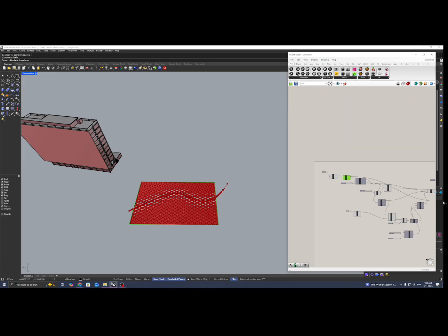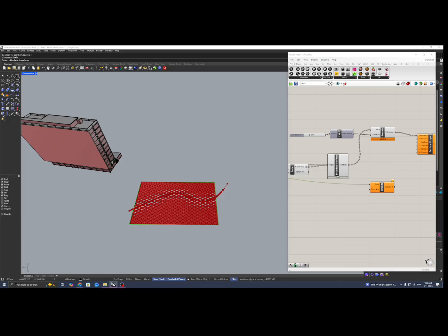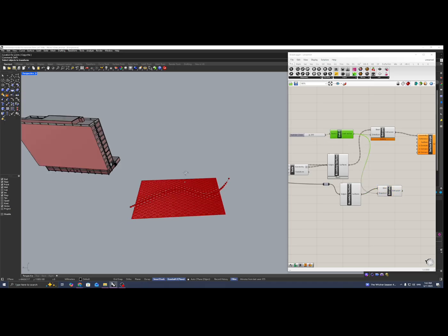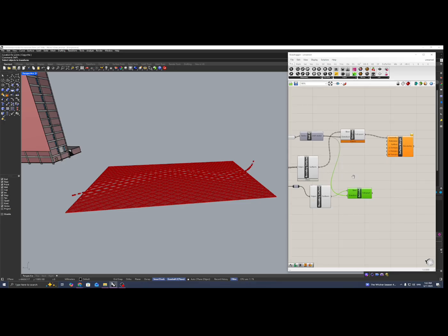So I'll just grab that one, drag it across into this space, into a boundary surface just so it's a bit easy to see. Boundary surface. So that into there, and this into there. And for the direction, we can just use the same unit Z with a 200. So now we have that box, we can just hide that. And now this extrusion can act as our reference.